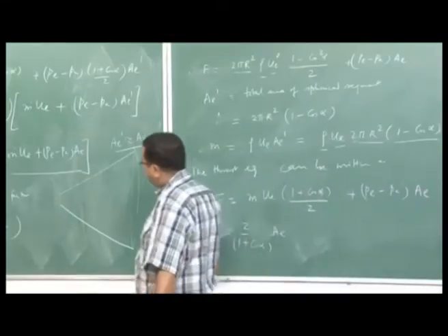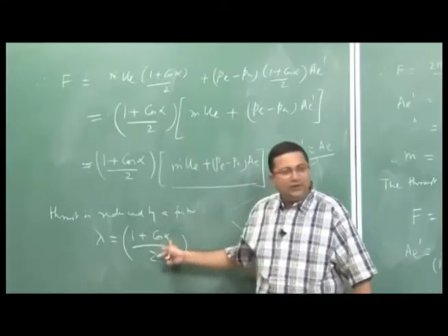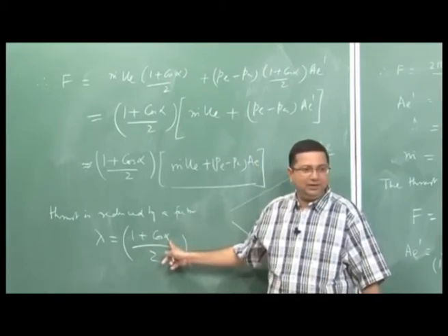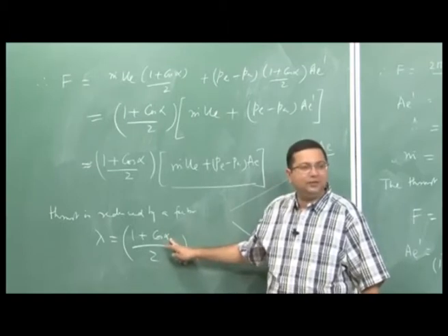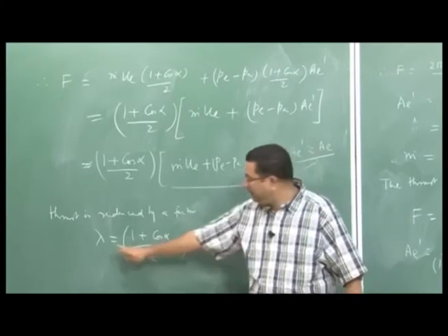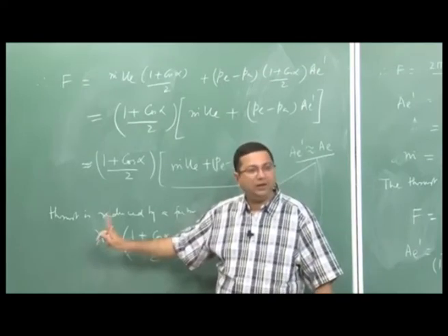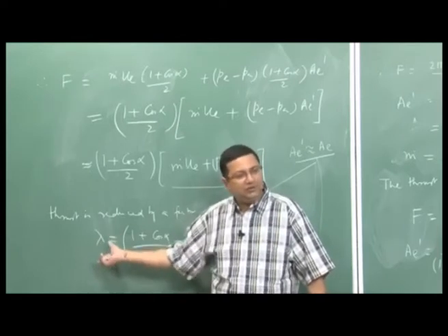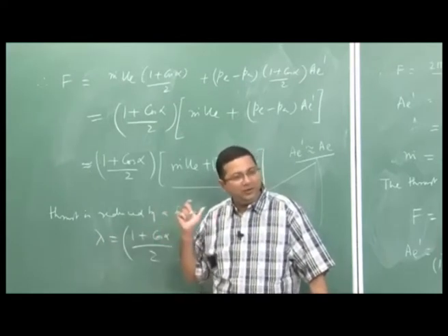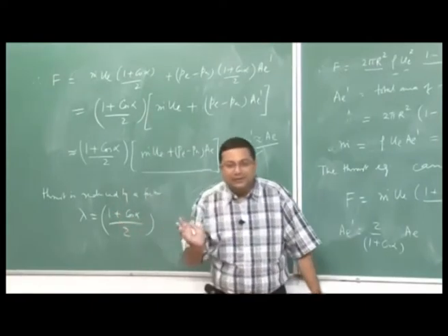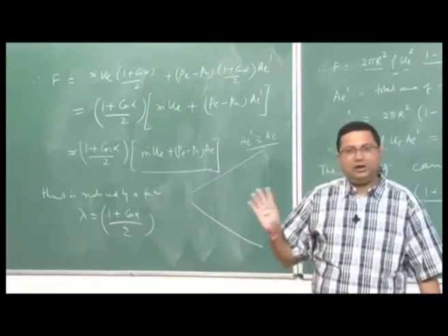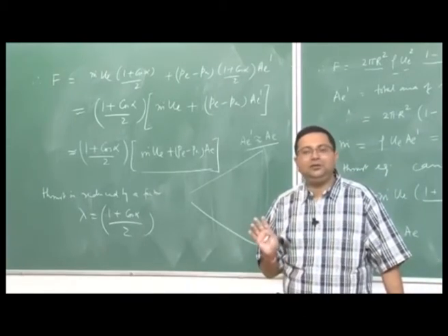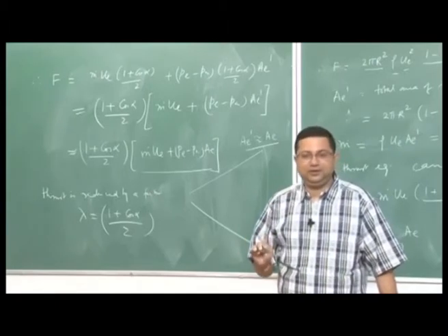Why are we saying that the thrust is reduced? Because cos alpha is bounded between minus 1 and 1. So, if cos alpha is 1, in that case lambda is equal to 1, otherwise cos alpha is less than 1, so lambda is less than 1. So, the thrust is reduced. So, straight away what we are seeing is that considering the 3D flow, not the 1D flow that we have been discussing, there is a reduction in thrust.